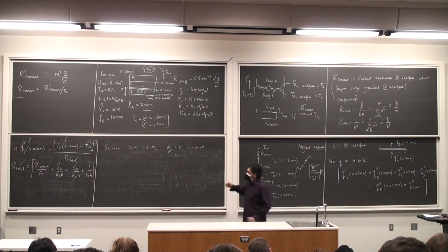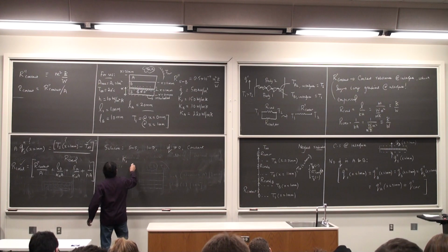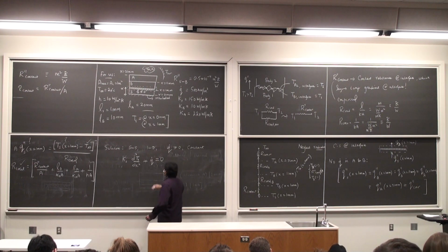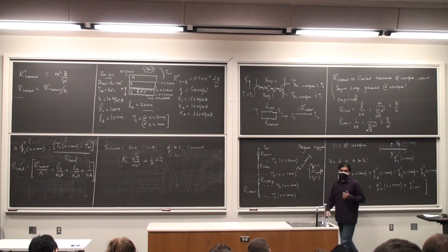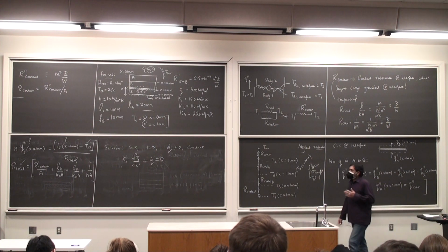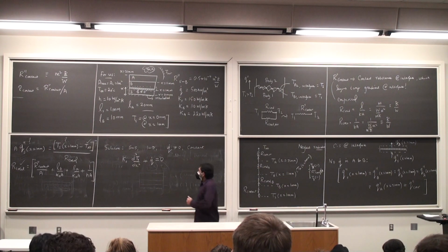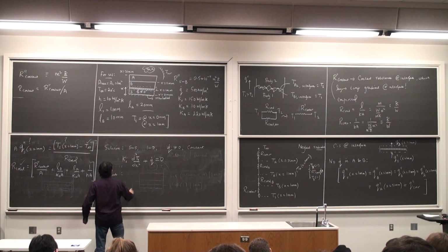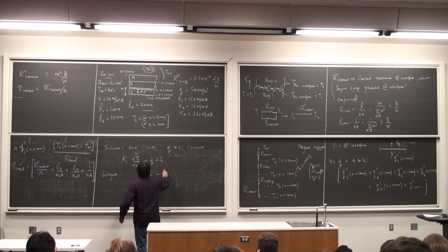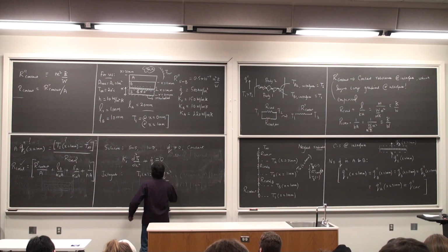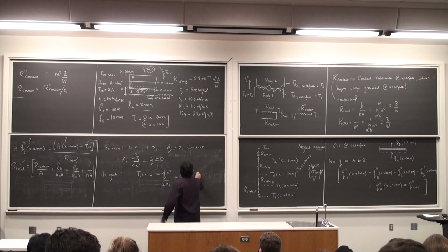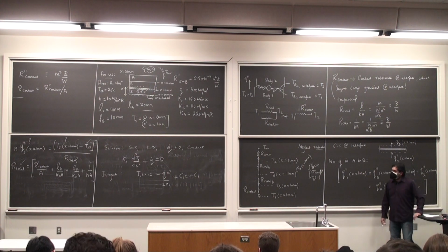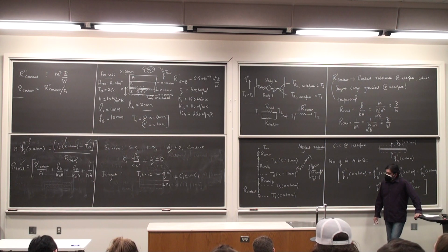So if I write the heat diffusion equation for this situation, I have the following. Silicon, d square T by dx square, plus Q dot is equal to 0. The dT by dt term vanishes. We have done this multiple times. You just integrate this twice. Okay, so integrate twice. Ts of x is minus Q dot x square by 2Ks plus C1 x plus C2. Alright, so two constants.